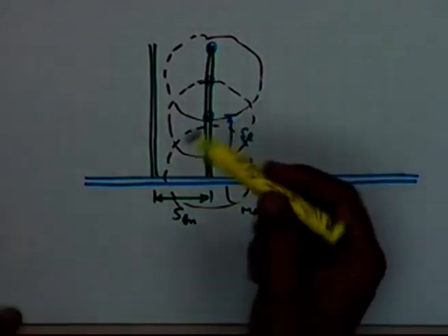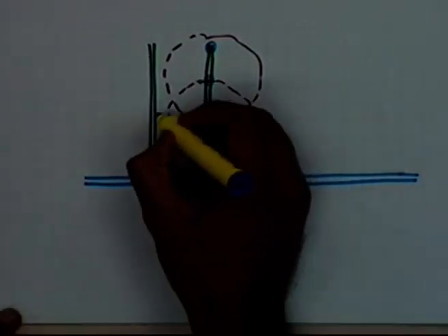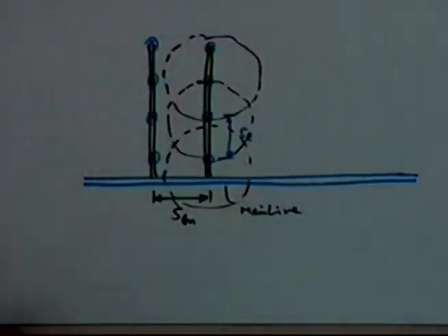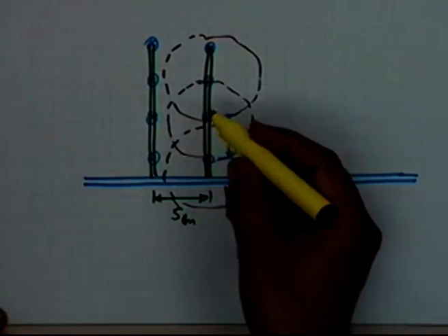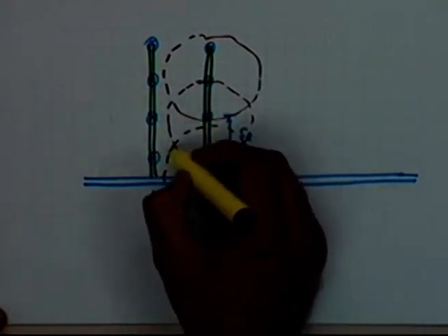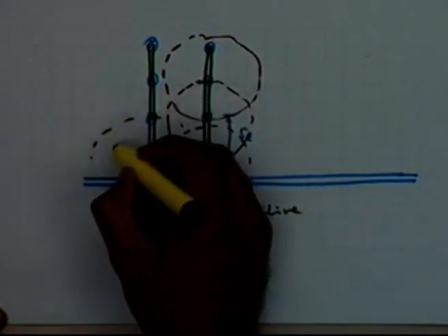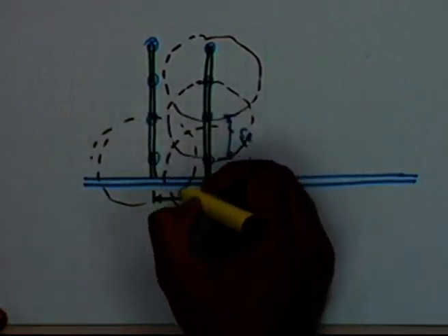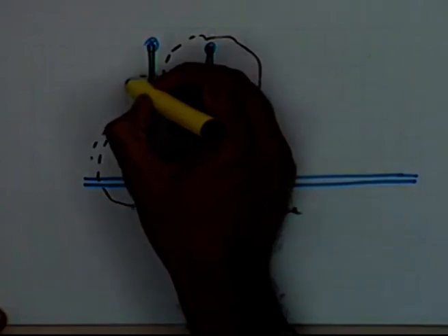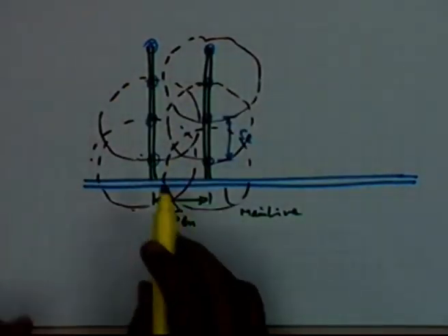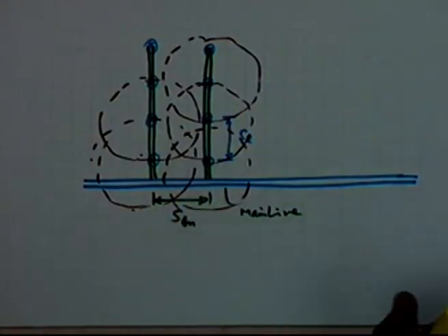Similarly there will be more sprinkler heads here, and the influence areas of these individual sprinkler heads will also have overlap in the other direction. So this total overlap will decide the net effect of the water application at that particular level.